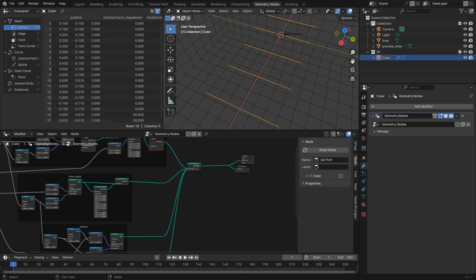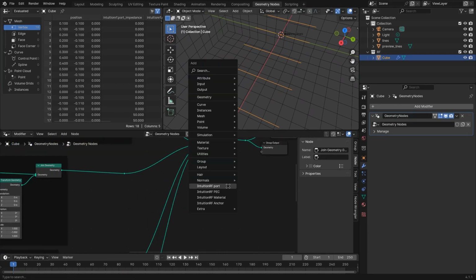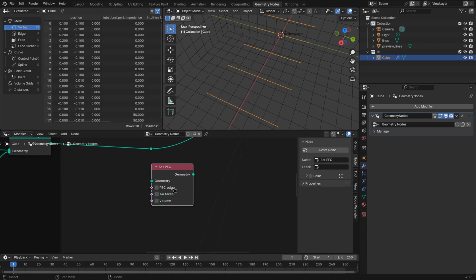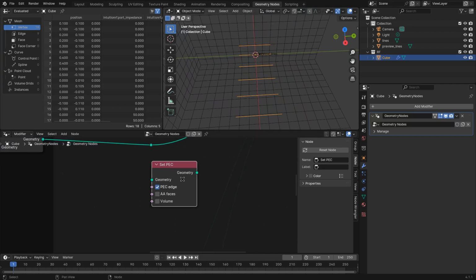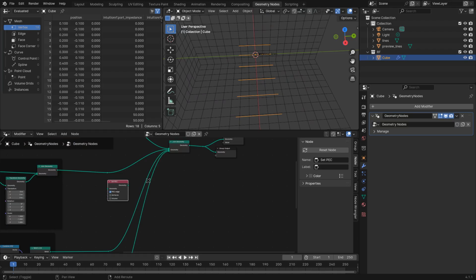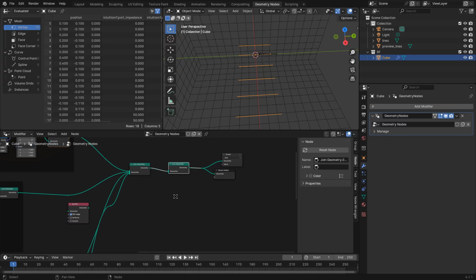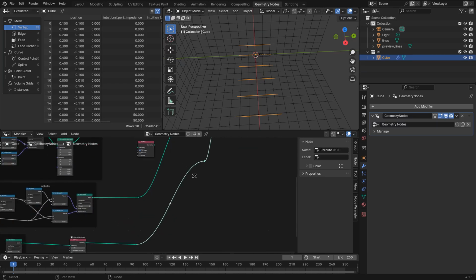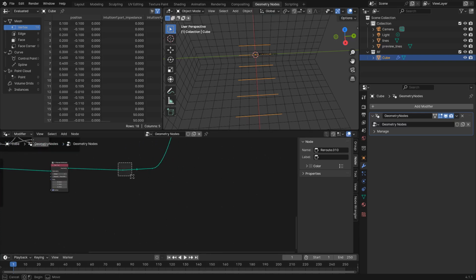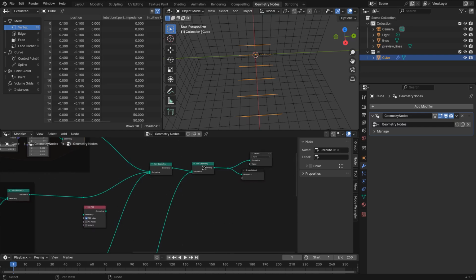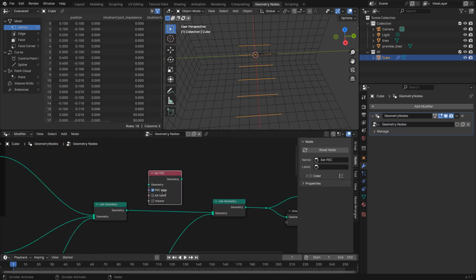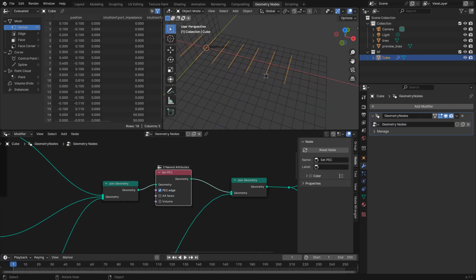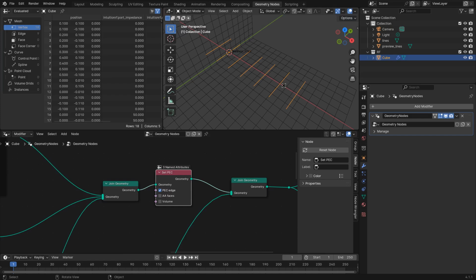Now we can define everything else to be a perfect electrical conductor. So we can use this. And now we can choose whether we want the edges of the mesh, the faces, or the volume to be the conductor in OpenEMS. So in our case there is only edges, so I'm going to use edges. And now what I can do is actually split this like this, and I'm going to cut this. Okay. This way the port is not defined as an electrical conductor, so I can have my port node here, merge everything one first time, and then add the port after. Okay, and now we can move our perfect electrical conductor, put it here, and all should now be defined as metal conductors, as edges. Okay.